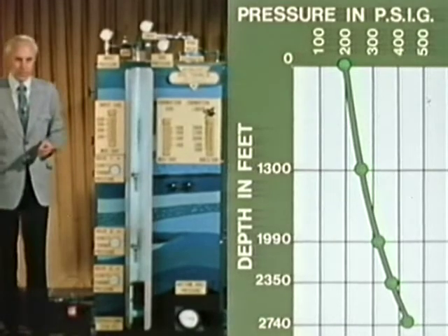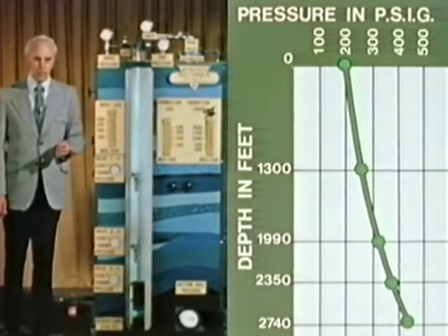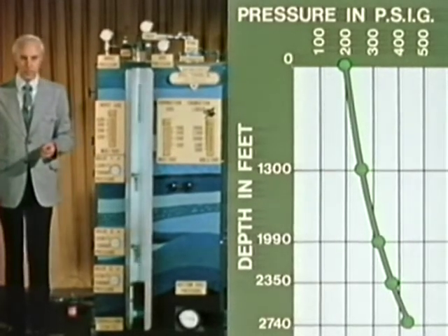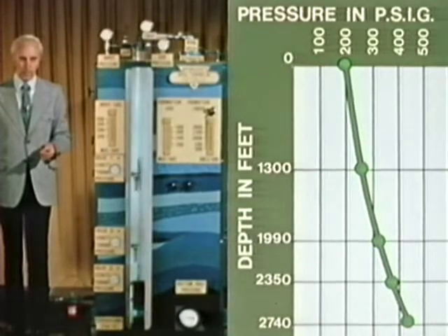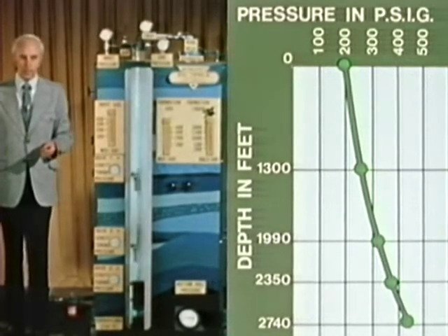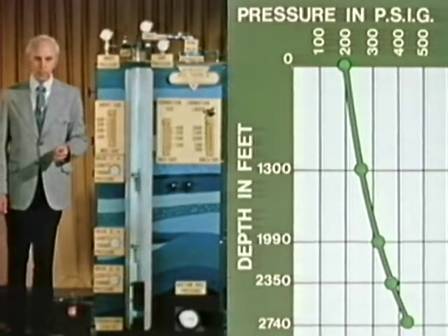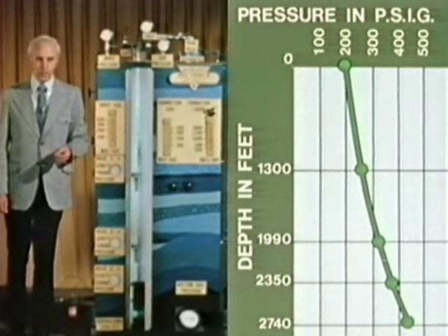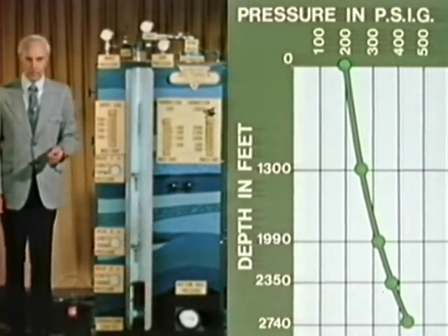This represents a gas to liquid ratio of 400 cubic feet per barrel. The word gradient simply means rate of change. Hence, a flowing gradient curve is a curve showing the change in tubing pressure with well depth as a well is flowing.